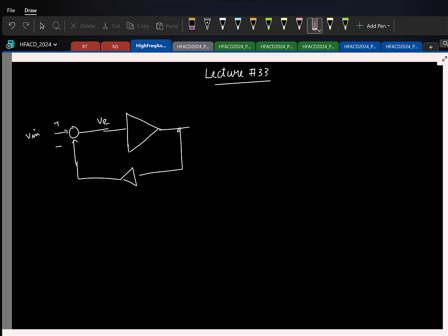And to be more technically right, we saw in the last class the negative feedback loop generates this error signal. And how is this error signal related to the input signal? If this has a nonlinearity f, it was related to the inverse nonlinearity. So that is why when you follow it up with the actual nonlinear system, it kind of cancels, right? Great.